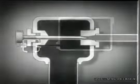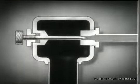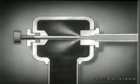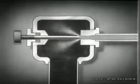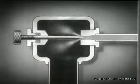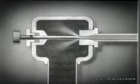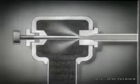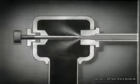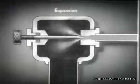The thermal expansion valve is simply a small adjustable opening. As the liquid refrigerant passes through the opening in the valve, it breaks up into a fine spray. At the same time, it enters a space larger than it occupied before. In this larger space, there is less pressure, and the refrigerant expands. This drop in pressure makes it easier for the refrigerant to vaporize or turn into gas. This is the first stage of the refrigeration process, expansion.